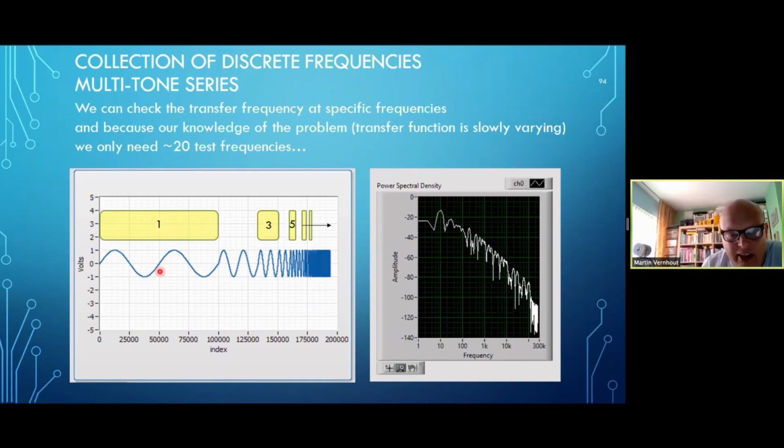Now in this case, it shows that for the lowest frequency, you actually claim a lot of time. For a higher frequency, you have less time. And that means that your power spectral density, the amount of power which is there on the frequency axis, so with the FFT in place, diminishes strongly with higher frequency. So the power here is around minus 90. If it is over here, let's say minus 30, you can estimate the ratio of power at low frequencies to the power at the high frequencies, which is many thousands of times.